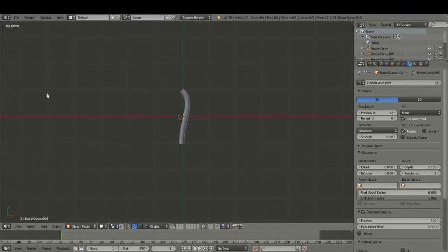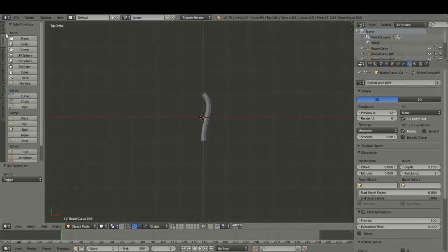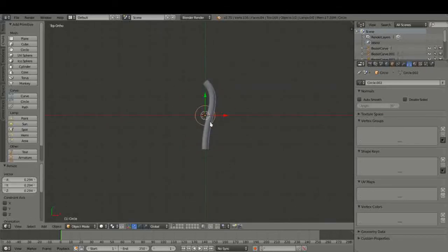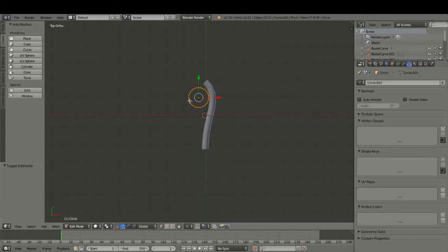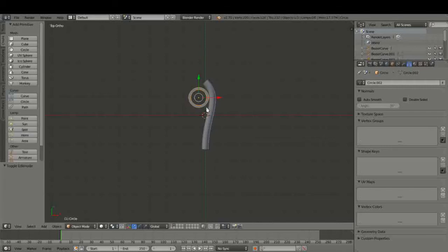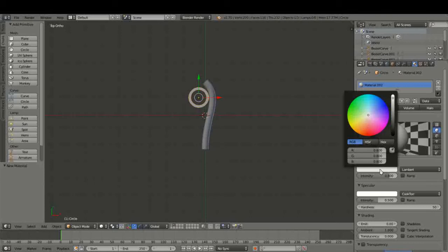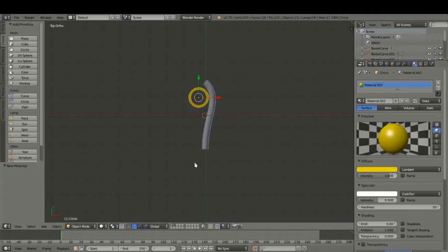The circle I'm going to add, pressing T, is from the mesh, so not the curve, Bezier Curves. So it's one of these circles, and I'm going to scale it, bring it over here, and then I'm going to select tab, and then press E and scale. I'm extruding it inwards just to give it some thickness. I'll explain just now. The reason why is so that you can see what I'm doing, because sometimes the YouTube image is not too good.